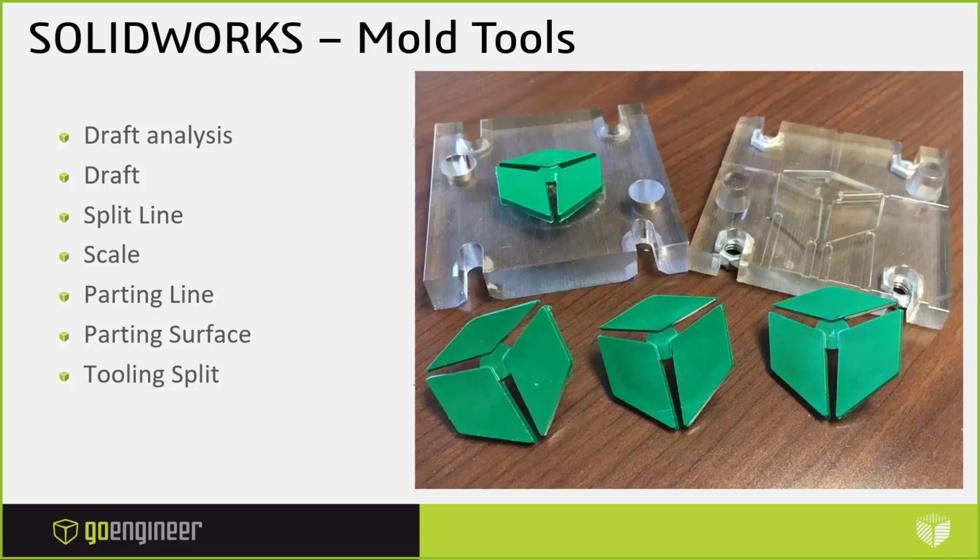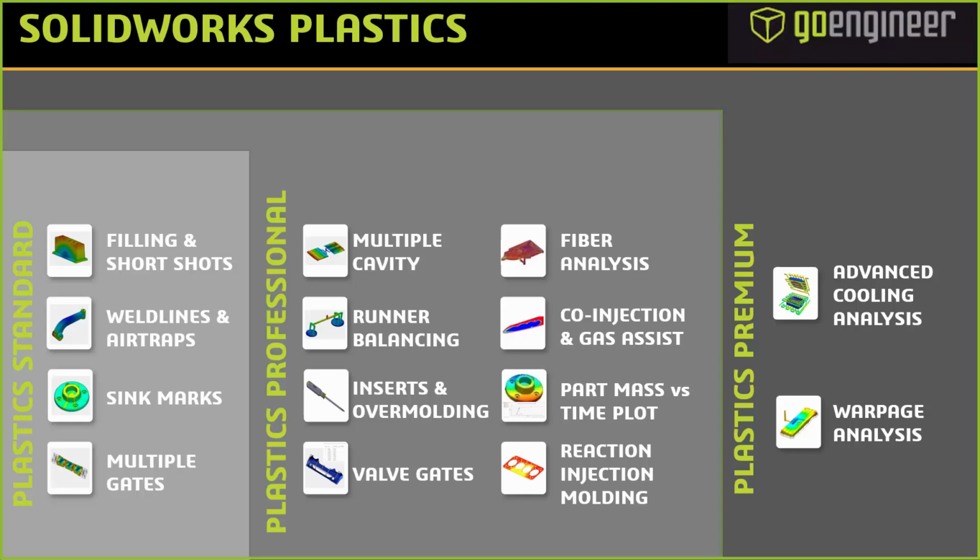So I've got my injection molded part now. What I wanted to do is look at, okay, I'm going to mold this part. I need to run simulation on it to see how it's going to fill. I need to see what pressure is required to fill this part, so I make sure I've got the proper gate location or sprue size to allow my little press to have enough pressure to fill this part.